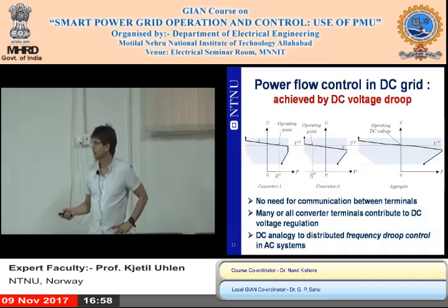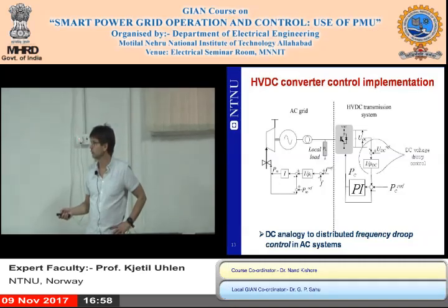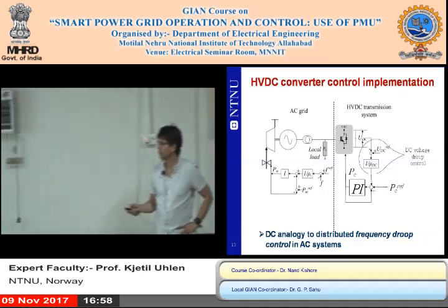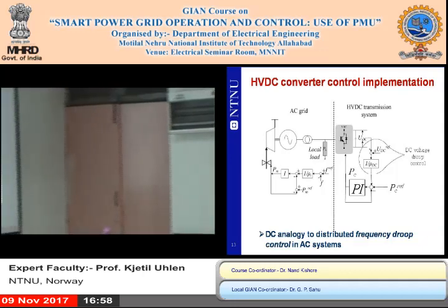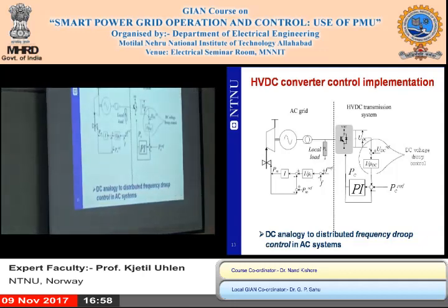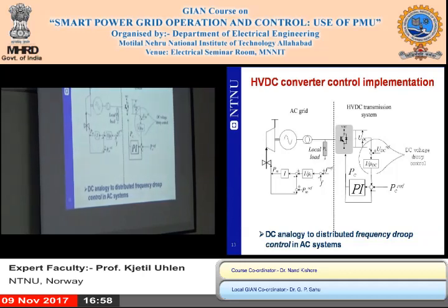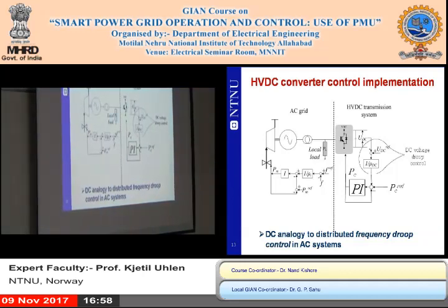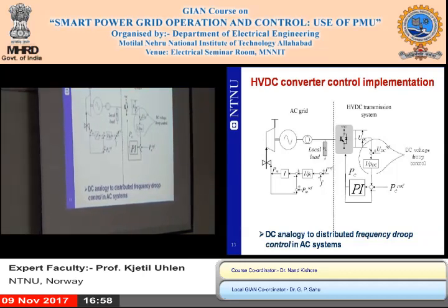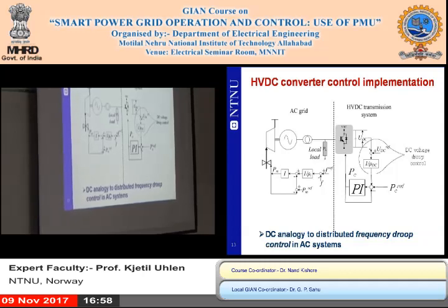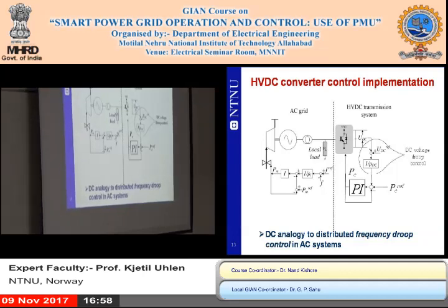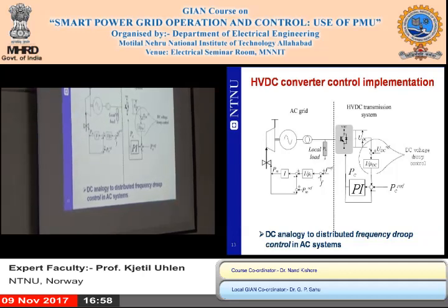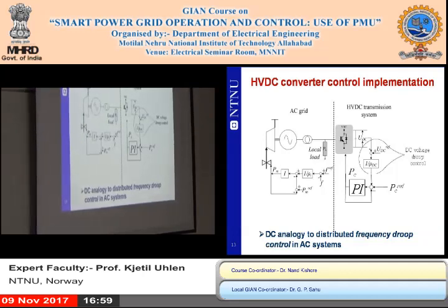So how do you do that? Well, you do it basically in the same way as for a turbine. The modern voltage source converters, and we are talking in practice about voltage source converters here. You cannot make a DC grid flexible and practical with thyristor converters.